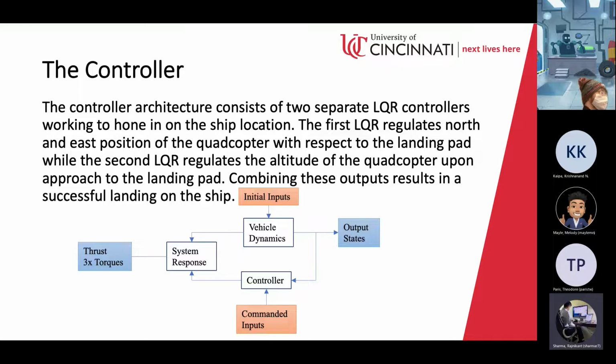Once it realizes it's within that state, it switches to the other LQR controller, where it will slowly descend to its target, hopefully safely. If it then moves back out of that situation for whatever reason and can't keep track, it will hold that altitude, so it won't keep going back down.